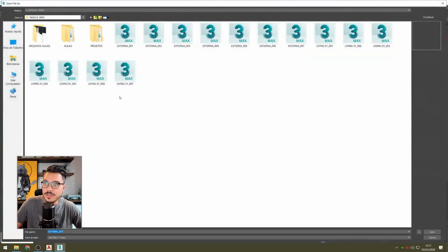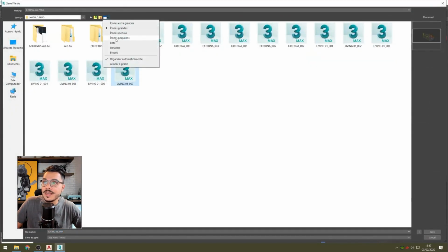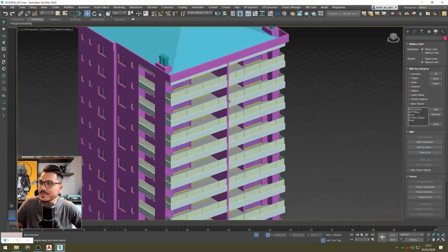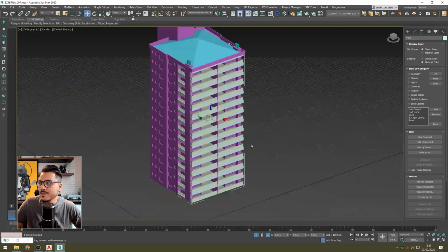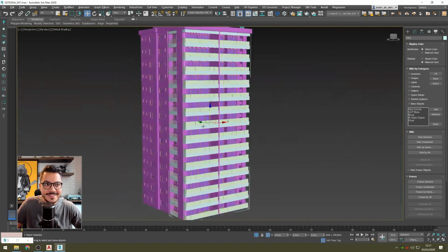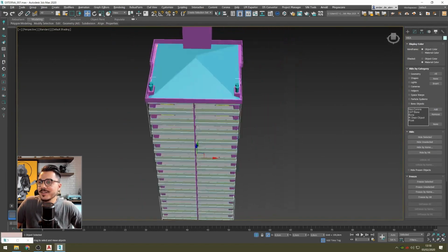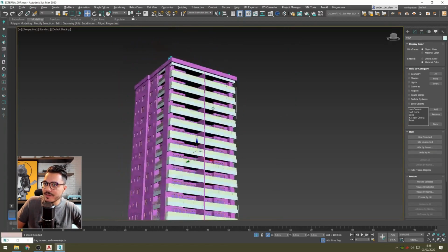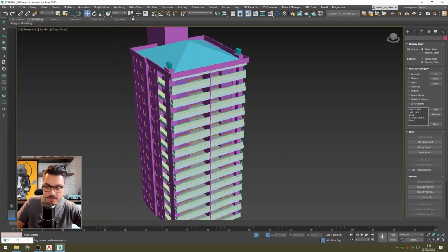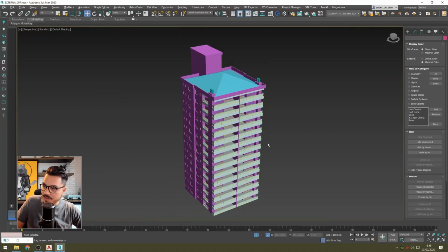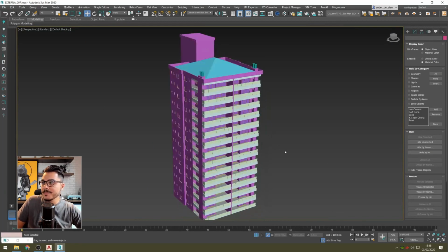I'm gonna even save this file and tell you how heavy that is, so that you can see it. File, save as, let me put it here, in detail mode, for us to see. It has just 6 megabytes, 6.9, 7 megabytes. It's not much. An architectural tower project is lighter than a chair block, okay? It must be lighter than that curves tool you modeled in the internal modeling class. This tower is probably lighter than that one, because of the organization of the polygon, limited number, and that we don't need at all more polygons than that for a facade image.